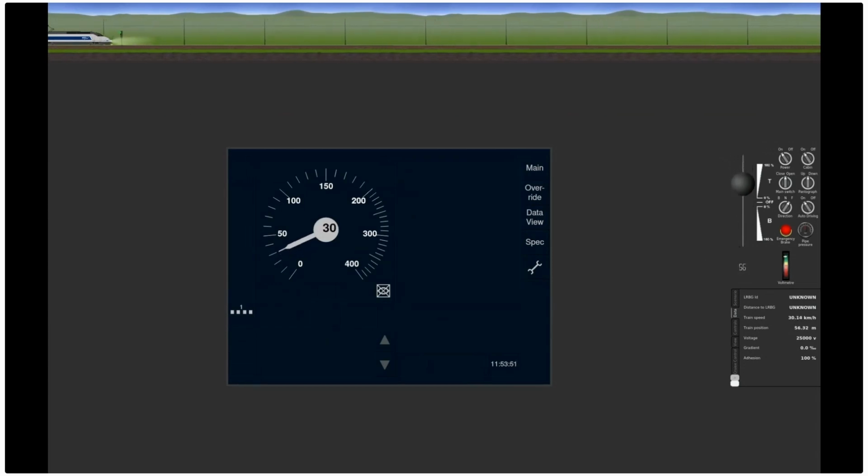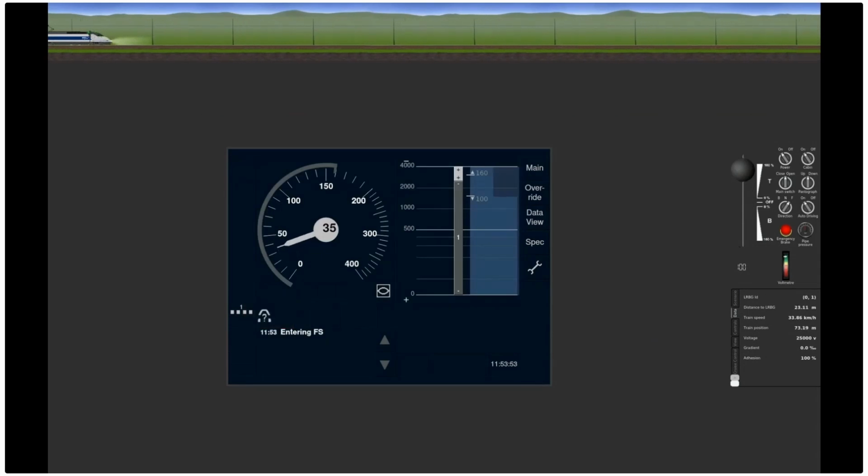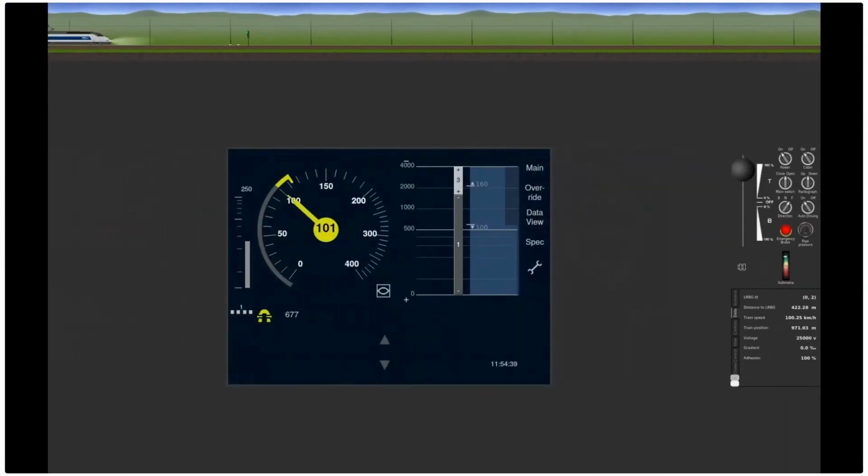The first passing balise group is sending the information about the stopping permitted in tunnels. The driver sees an icon informing that tunnel information is available. The driver presses and sees an announcement and distance to the start of this area. The train is approaching the area which starts at the entry of the tunnel.